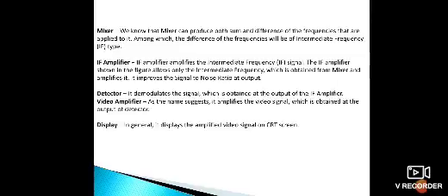That means the local oscillator gives some signals, and at the same time the RF amplifier gives some signals, so the mixer provides both the sum and difference of the signals, among which the difference will be of intermediate frequency type. Okay, so from the mixer we get the IF frequency range, and those frequencies are connected to the IF amplifier.